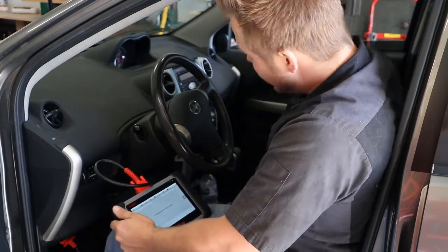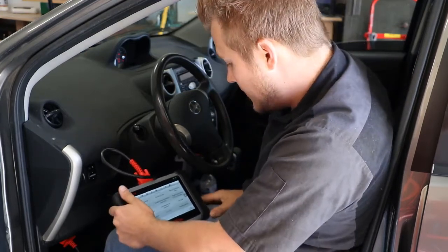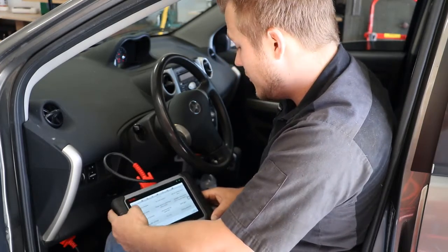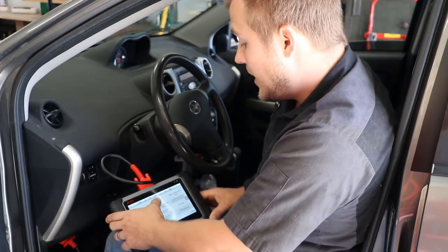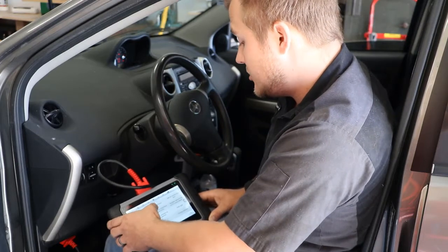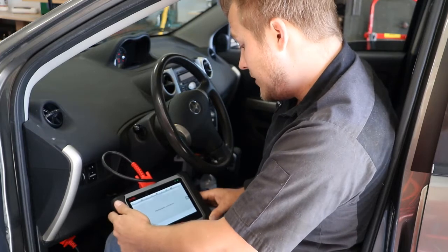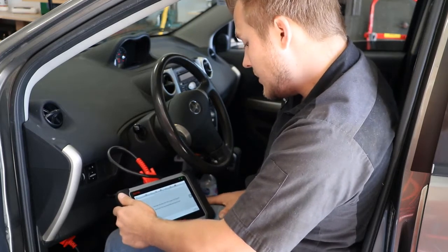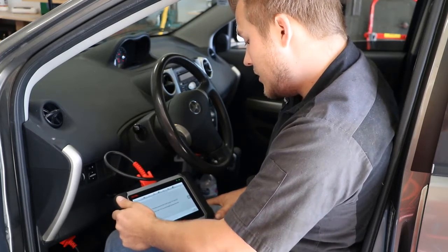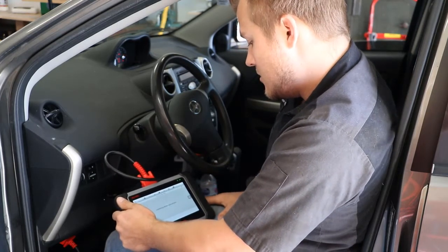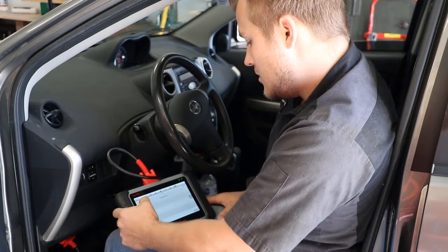When we go to the active tests, we should be able to test all of the systems we have here. We have injector volume, air fuel control, idle air, fuel pump, and purge VSV switching valve, which is the purge valve. So we're going to try to test the purge valve. Let's see what we got. Purge valve VSV on off. Only EVAP VSV is commanded during the test. Okay. See all data.